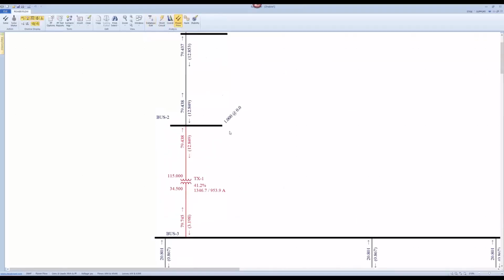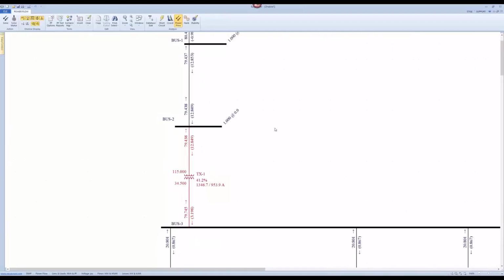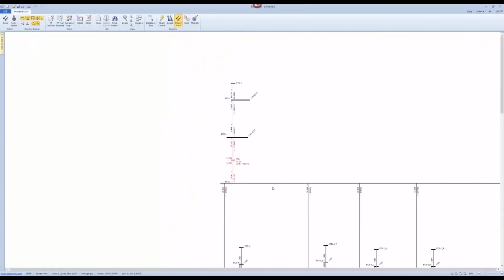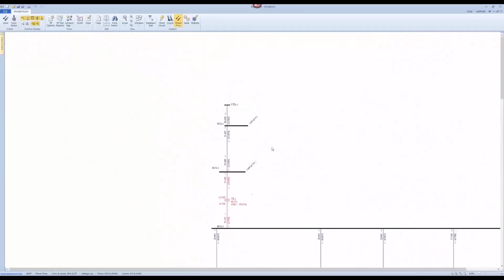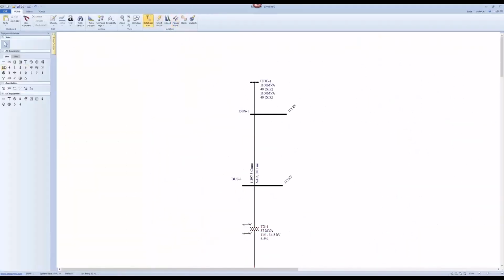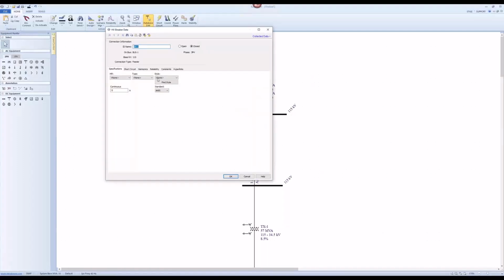So in this case, if we are done with this model, let's first ignore the battery energy storage portion and only build the PV portion. Then we'll see if we'll have time to build that because it's nothing but the same thing as copy paste the whole design, just enter different harmonic spectra, right? Now let's go back and put PCC breakers over here. Typically, we would like to put the PCC breaker right at the utility bus, right? Because that's where you connect with the utility.